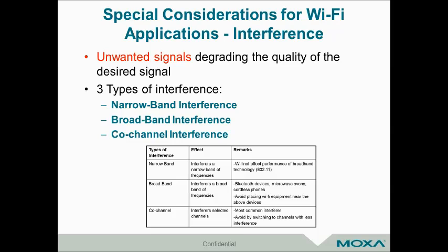We really want to make sure that you guys are aware that different applications can use different types of antennas. If you're doing what we call a typical AP client topology, which means that you have a point to multipoint, or one central access point that's allowing access to many devices, you're most likely going to want to look at what's called an omni or omnidirectional antenna. This type of antenna broadcasts at 360 degrees, and the radiation pattern looks like a donut. This is the type you use if you have many, many devices scattered throughout your facility that you want to give network access to.